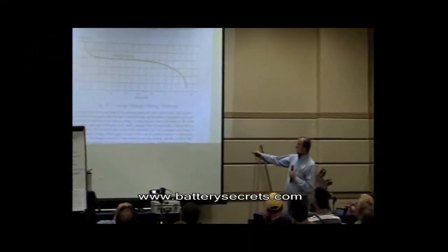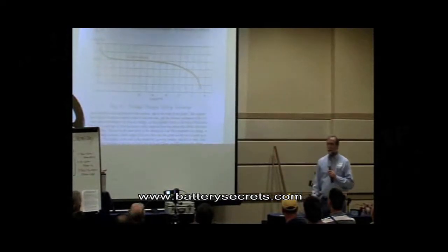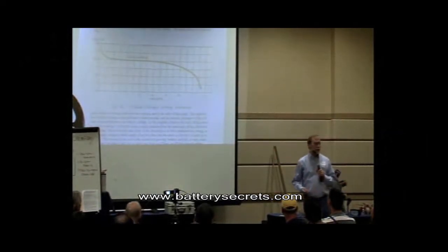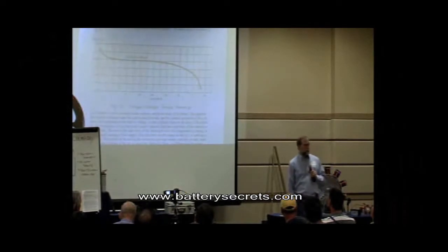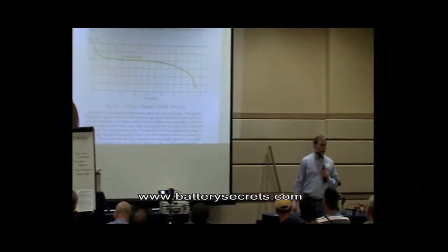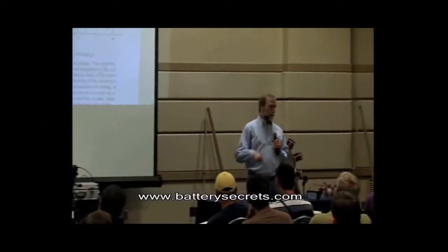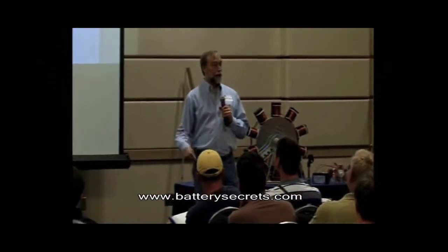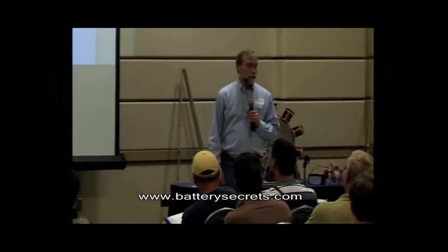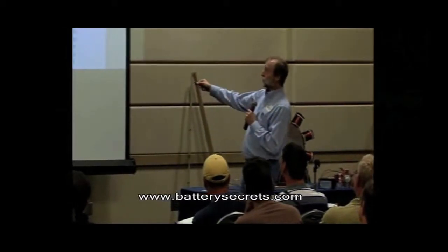So this 2 volts represents what we'll call the electrical potential difference between the plates. And it is also represented by the actual chemical difference between the plates. In other words, one plate is lead oxide, one plate is lead, and it's literally the electrical difference between those 2 substances when they're sitting in sulfuric acid that is this electrical potential.